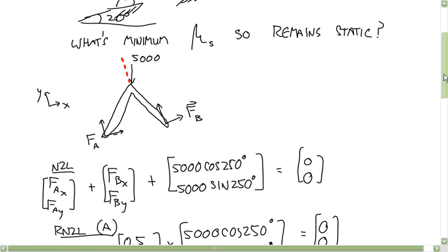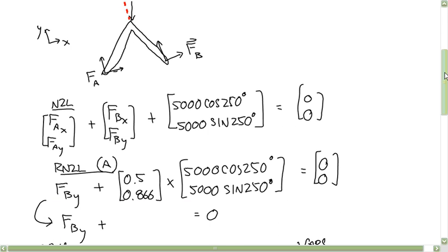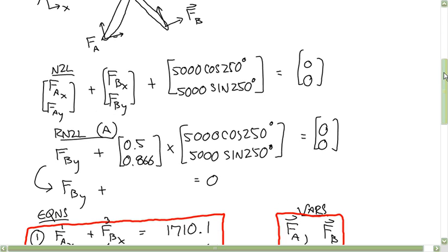Okay, so because of the way the structure is shaped, I think the math of everything is quite a bit easier if you do use this rotated coordinate system. I should have made it easier in the other coordinate system, so you had to use the dot product thing. But isolating the whole structure, I got three equations for four unknowns. You can't solve anything yet.